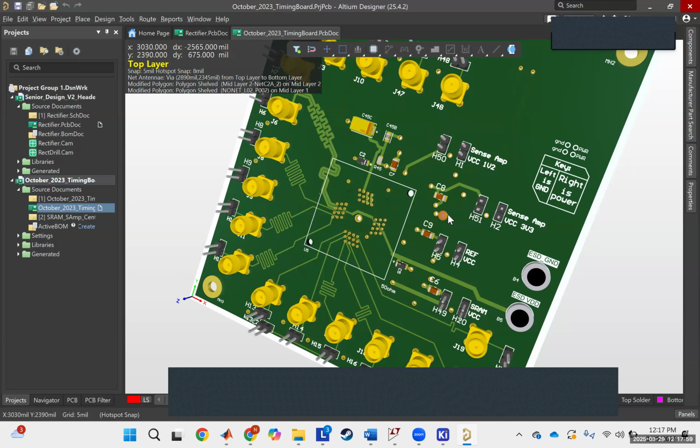And then you have your components set on your board, but then you go to the other side of the board and try to do the same thing. Then you put it back in the solder oven. That solder that you already put down is going to heat up again and reflow.